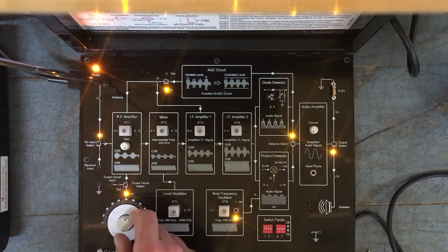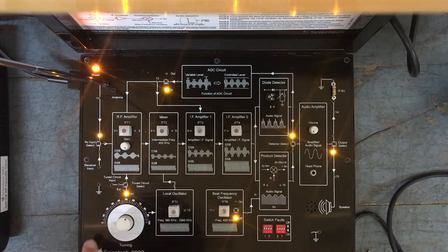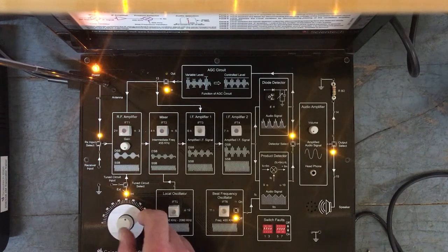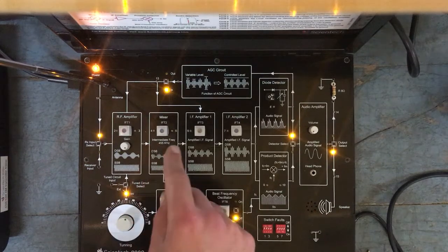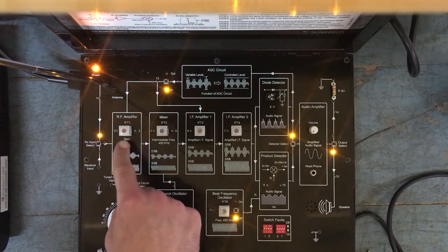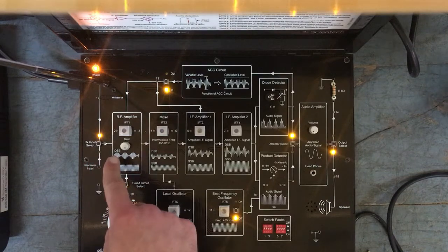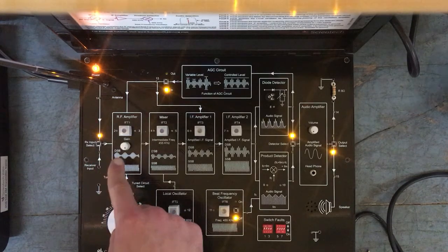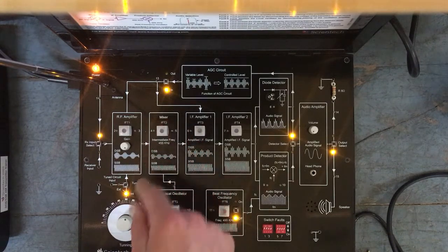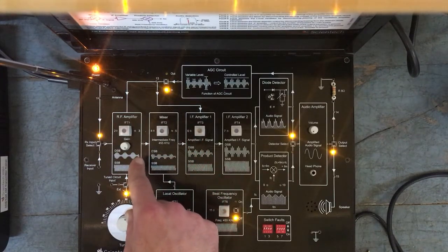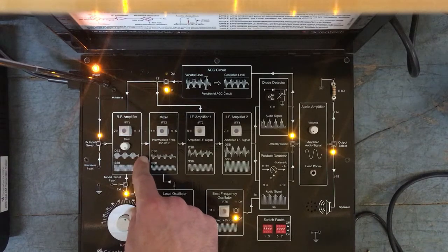So once that is tuned, which is around in this 0 to 100 scale, around 55, 58, right, then our RF amplifier is detecting the amplitude modulated signal, but it would amplify the frequencies which are more near the 1 megahertz range.